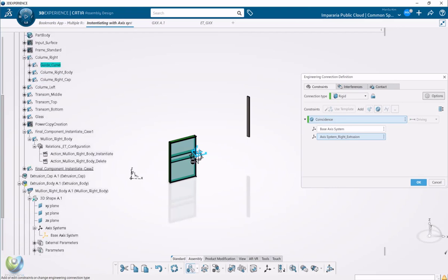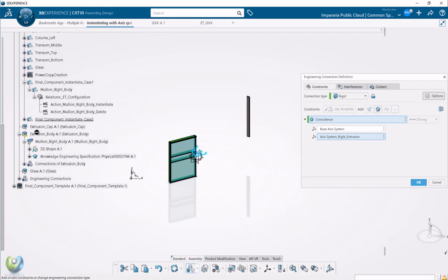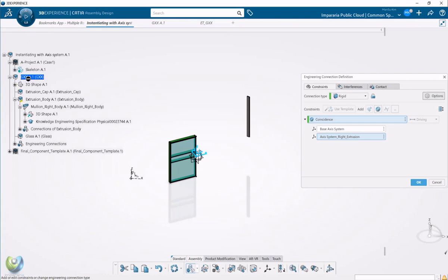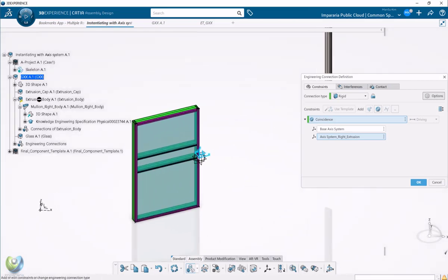The problem here is that not the final component is moving, but the assembly level is moving, because I'm accessing the assembly here. This is the sub-assembly, and the final component is located under the sub-assembly. So this doesn't recognize it if you don't check the contextual recognition. Imagine that if you have many Boolean and transform features under this sub-assembly,